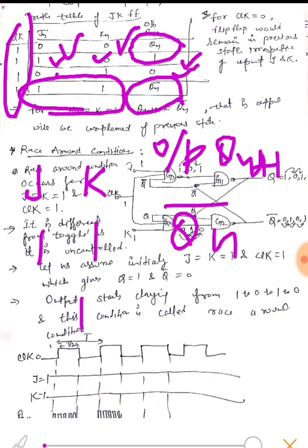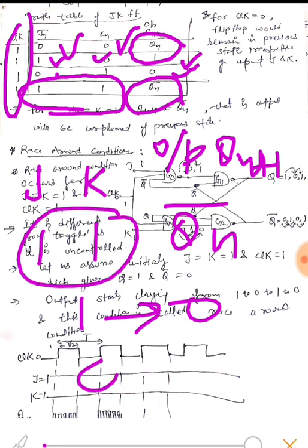If it was 1 previously, then it would change to 0 on providing the input 1 1. If it was 0, it would change to 1. So it will toggle, or it is not exactly toggle. We will see that it will race around when the input is 1 1.